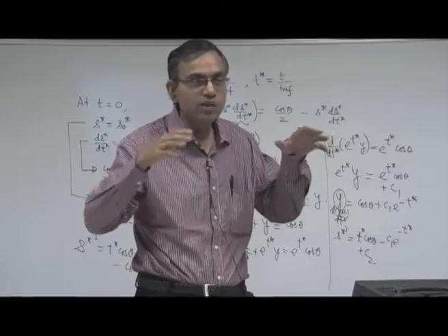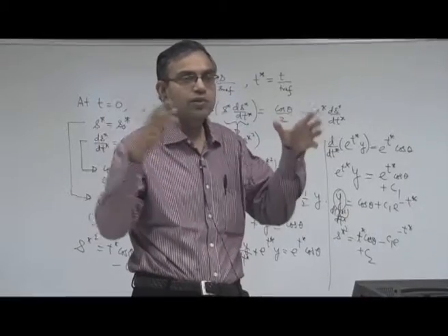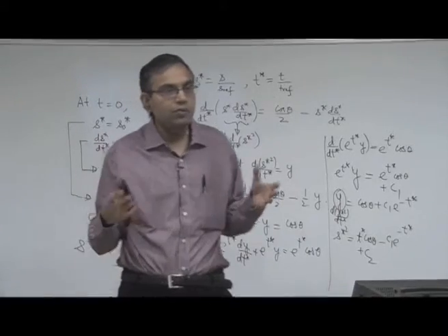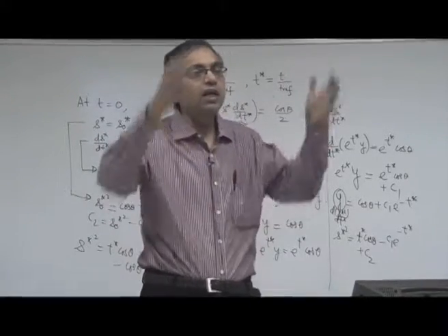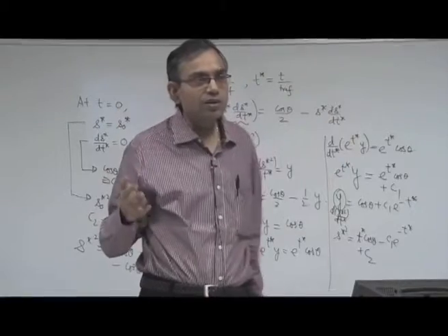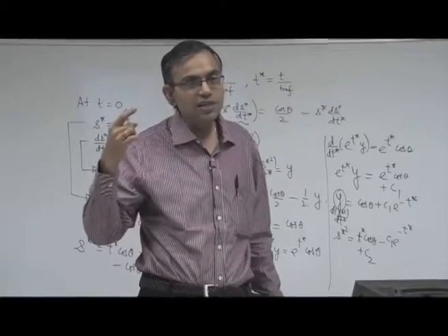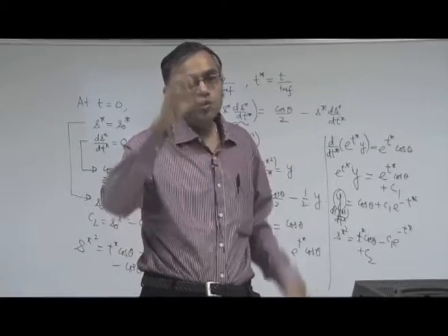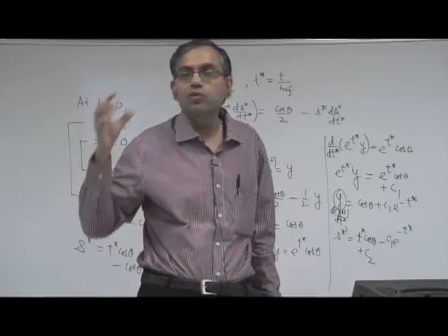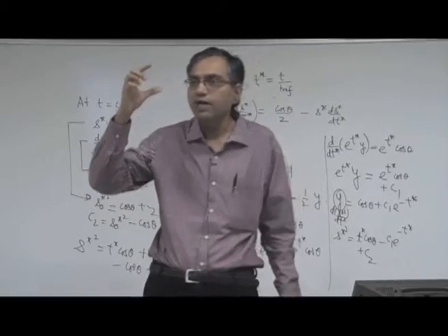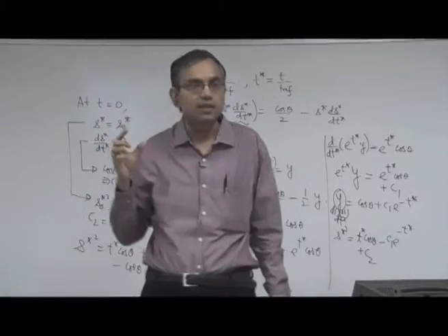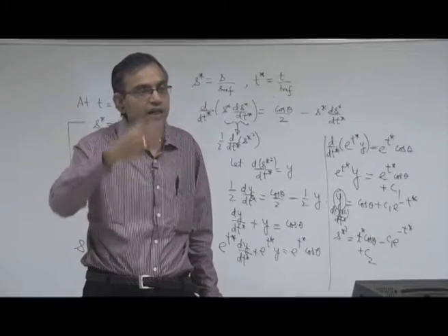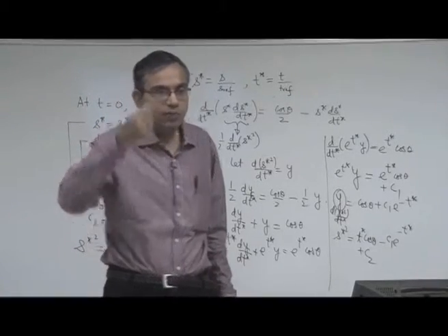microfabricated surface looks, maybe through an atomic force microscope, and you will realize that you can forget about the paradigm of an ideally rectangular channel. The surfaces are undulated in a very peculiar way, where the notion of an average height may become questionable. An average height may not represent the physical reality. So there are uncertainties in the height, and there are uncertainties in the flow rate measurement.